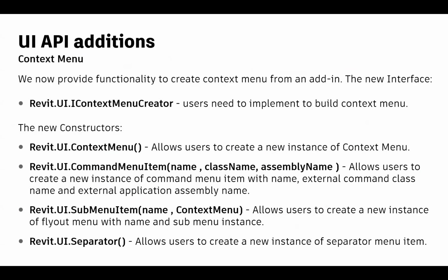Some additions to UI API. It is now possible to programmatically create a context menu from within the application. The new interface, IContextMenuCreator, users need to implement to build the context menu. There are new constructors for ContextMenuItem, for SubMenuItem, and for the separator.